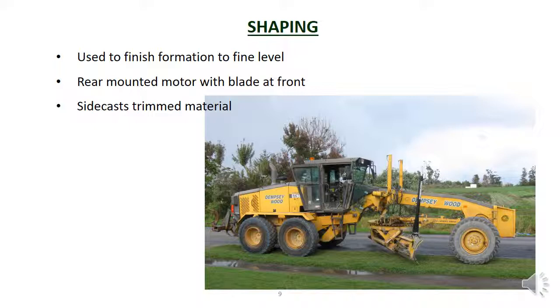The operator normally tries to keep some soil travelling ahead of the blade to fill in any low points. The turntable, and therefore the blade, can also be tilted at an angle to the ground. This allows the grader to shape the ground as required. Most road subgrades are at 3 to 5% to allow water to drain away, and the grader has to provide that slope accurately. The blade can also be pitched forward and back to provide different sorts of cuts. These movements are all controlled by a hydraulic system.